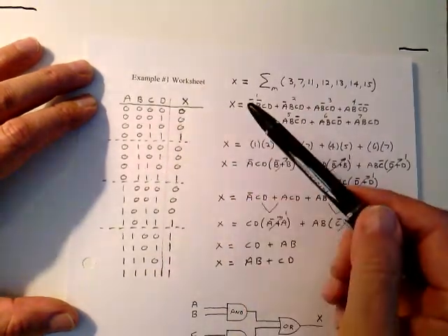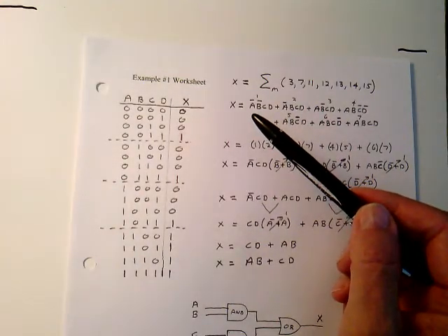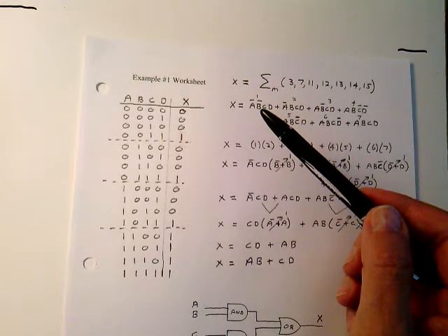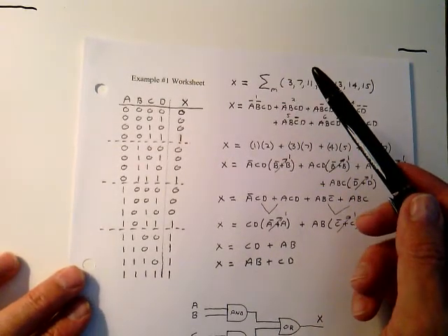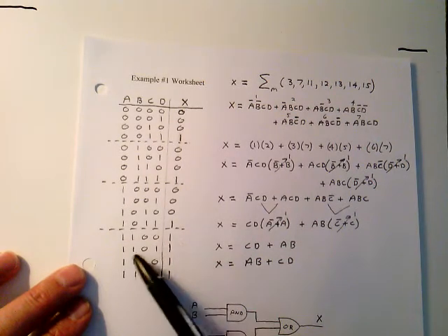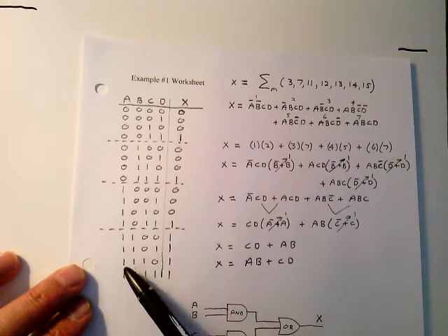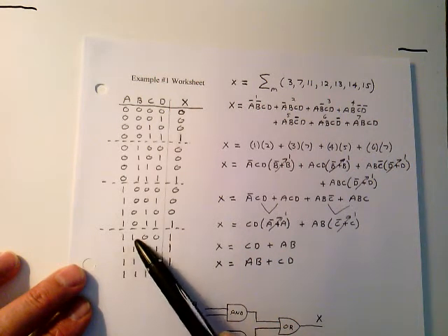Now, you read your specification. And what it says is, we'll go back and look, design a logic circuit using AND, OR, and inverter gates that will detect whenever tank A or B is too high. Well, where's A and B too high? A's high, B's high. There's an output. A's high, B's high, output. So we put fundamental product 1s in where the A and the B's are high.